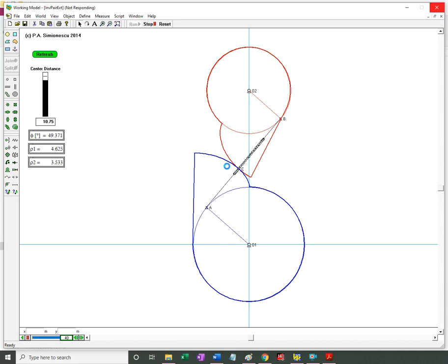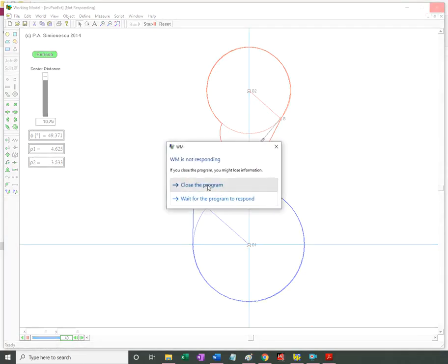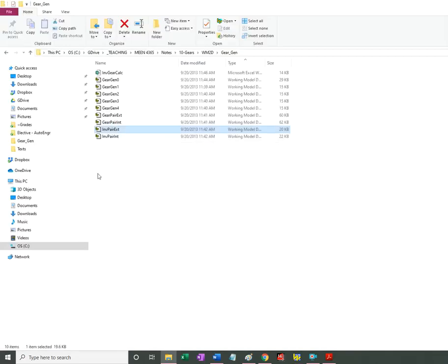With the moving point C I'm going to envelope other portions of the envelope, but still I get an involute shape to the teeth, and this explains why involute gears are not sensitive to center distance modification. By moving the gears away, the backlash is going to increase.